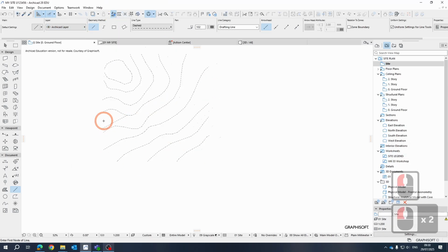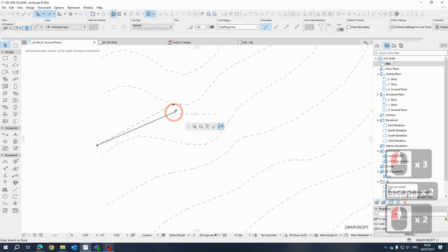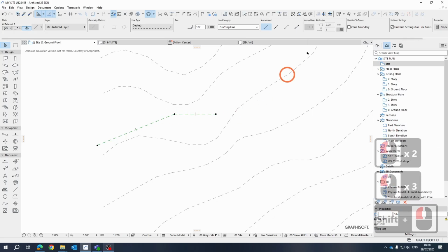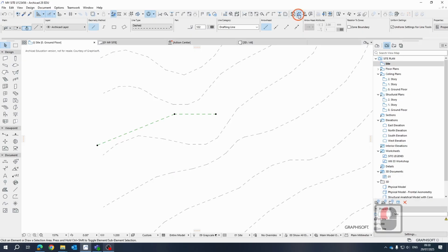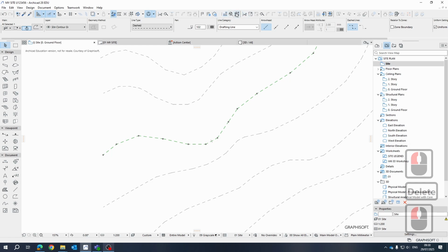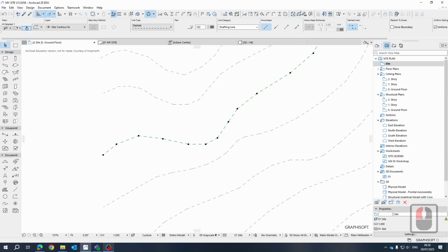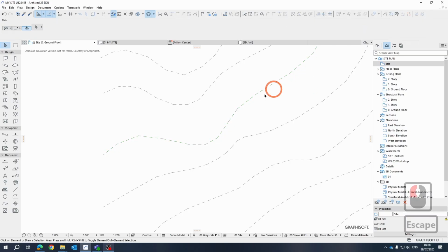And if you draw a bit of line work, at any point you can go and join these together. So you can select both of these, and you've got an option to join these objects together. Okay, so just remember, at any point you can go and make these objects. I just don't have the tools active because the layer is technically locked at the moment. So if you right click the layer, you can just say unlock layer here. Then you can see you've got these tools. So you can explode it again to make it separate objects, or you can then combine them. Okay, so you've got all of these tools to go and explode them.